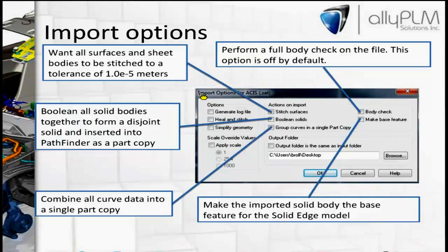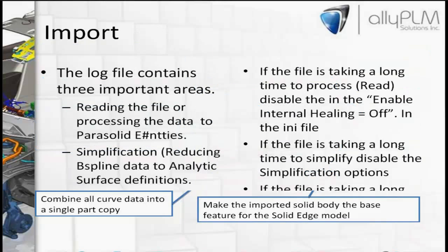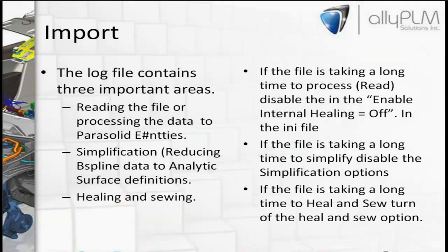And what that's saying is when I import this model, it'll create the assembly if you save it into an assembly, and then all the part files, or it'll just create the part file or whatever file format, if it's sheet metal or part or assembly, and it'll put all those files into this directory. That's where you specify what directory you want to put it into.